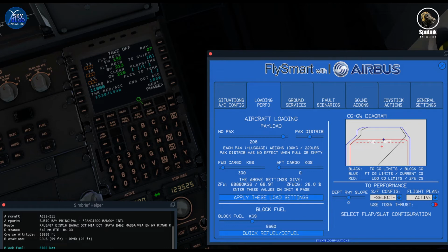So of importance, we'll do takeoff page. The first thing you should put is takeoff shift. This is essential when you're doing an intersection departure. The reason for intersection departure might be because it's faster to take off from there due to a shorter taxi, or as in the case in Manila runway 06, there is a taxiway construction or renovation in progress. For training purposes, let's assume that Subic is doing intersection departures.